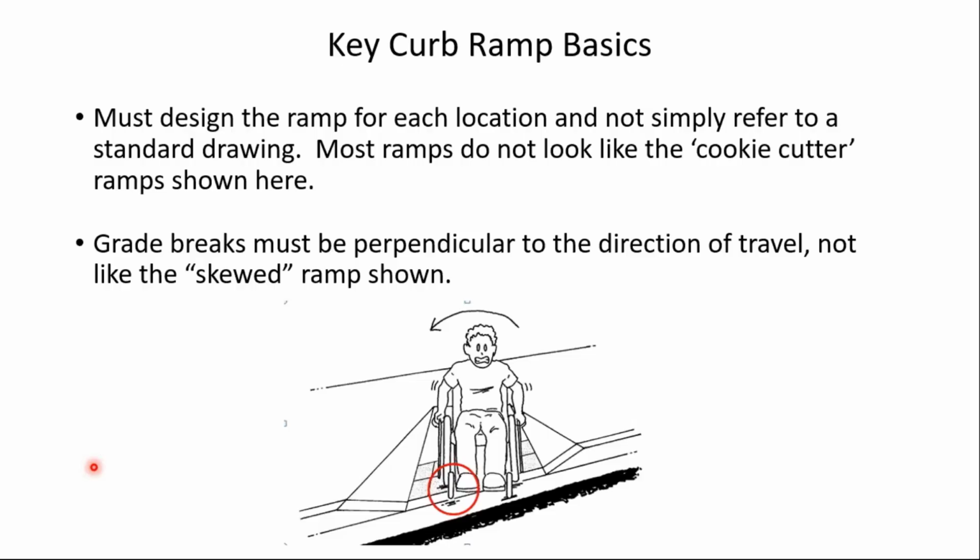Did want to go over a few curb ramp basics. I think we need to design ramps for each location and not simply refer to a standard drawing, because most ramps don't look like these cookie cutter ramps that I might show. And to me, the engineering work should be done ahead of time, not by the field personnel trying to fit a ramp in at a particular corner.